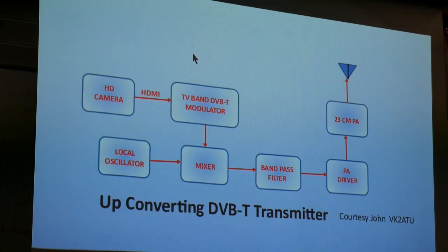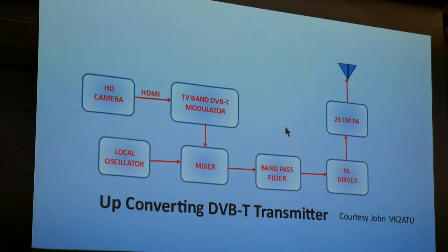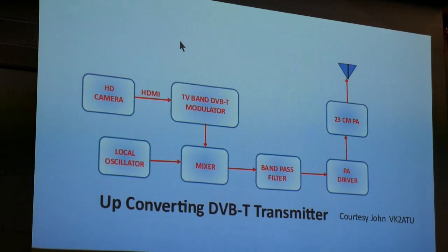So he gets away with it basically because he's running it at a fairly high bit rate, because he's got a good signal path up to Lawson, or he did have, and he could run at a high bit rate. His signal to noise was so good that he could use one of those big constellations. He was using 16 QAM, which is not so big, but you can get away with it. Then you don't have to run the encoder so hard.